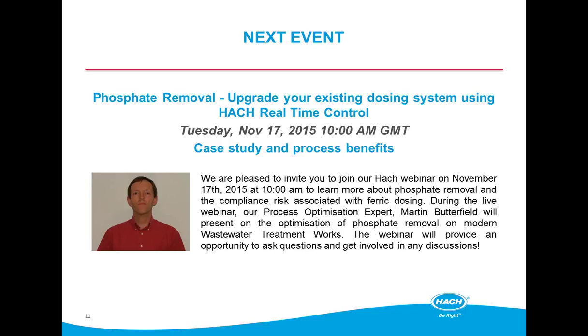What the operator doesn't want to see is somebody who's come on the plant a fortnight ago telling them how to run their plant. That's not the right way to approach it, because there may be things that we need to consider as part of the commissioning process, and the operators, by and large, do know the conditions of the plant well. It's just helping them understand that the correct DO set point for 5 o'clock in the evening, say, is not the same correct set point for 5 o'clock in the morning.